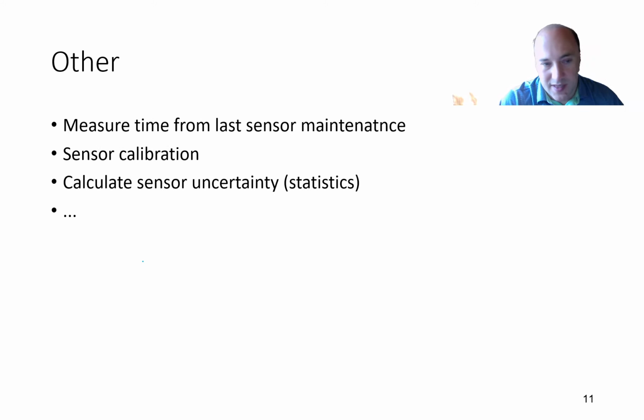What are the other methods? We will cover only one of them. Those other methods are typically not based on some mathematical description, although that's not entirely true about this, not at all. But they may use something else. For example, if we want to validate the signal from the sensor, we may perform sensor calibration. So we will schedule a calibration every 3 months, or every year, for example. By calibrating the sensor, we make sure that it measures properly, it's working, and it is within our specified accuracy. So this is not a method that is based on some online estimation, but it's also a method that allows us to validate the sensor from time to time.